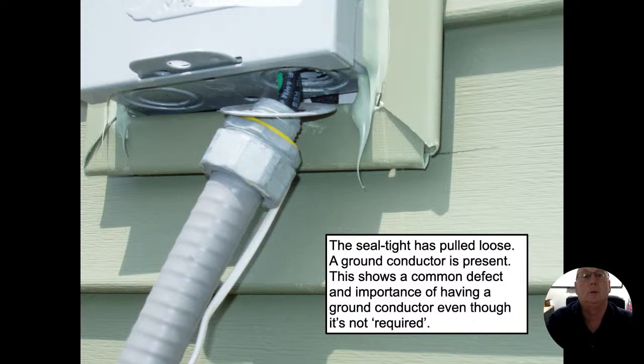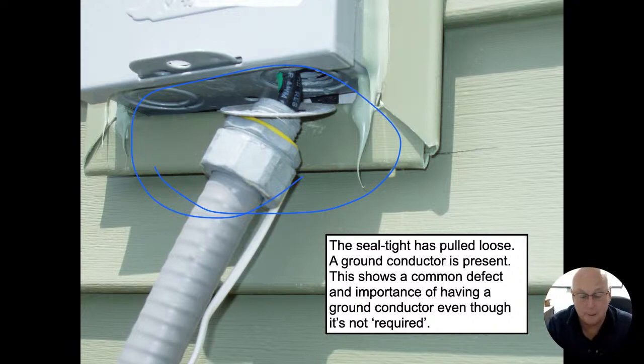And this is what we're looking at here. So here our seal tight actually came loose. I've run into connections for this seal tight or liquid tight where the connections themselves are plastic. I'm talking about this nut right there, where that thing's plastic. In which case, even if it is connected, I can't use it as a ground at all, because the plastic will break the ground going into the air conditioning unit. So I have 2 energized conductors in here, and I do have 1 ground conductor in there. There is not a neutral conductor going through this, but again, if it feeds my air conditioning units, I don't have to have that.